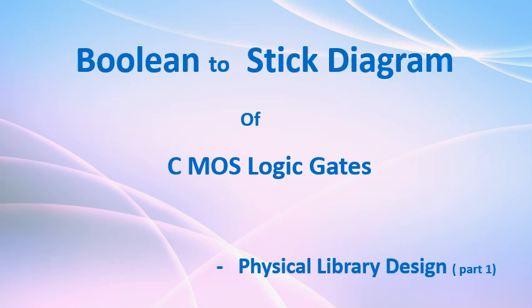In VLSI design, a library serves as the foundational database that holds pre-characterized information of standard CMOS logic gates. Library contains characterized models, using which a design can be simulated, even before its fabrication. Logic gate model design involves various steps like Boolean form functional expression, CMOS level circuit, stick diagram, and the physical